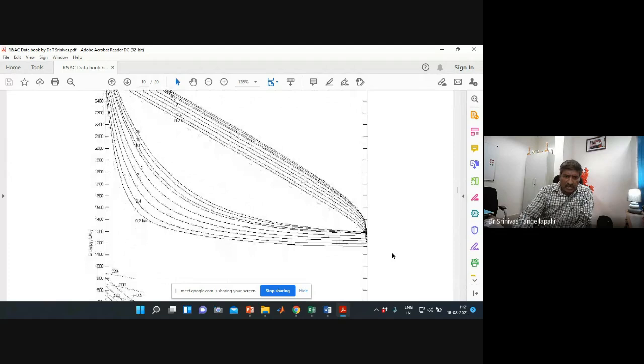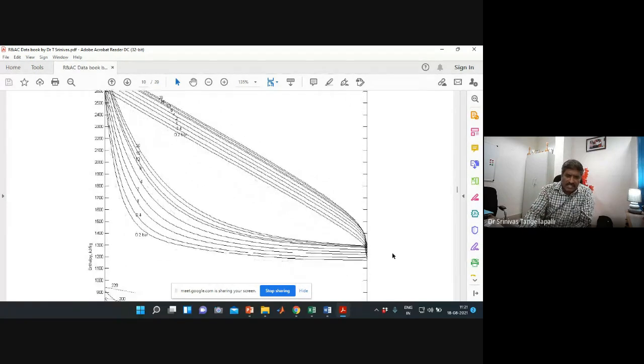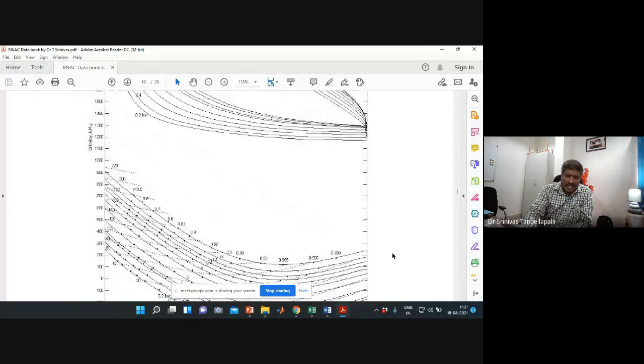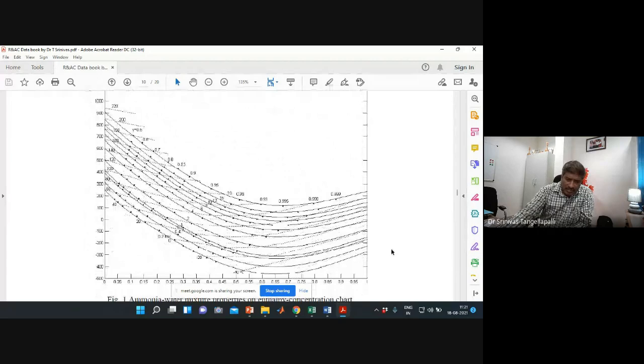Also, I am going to include one more chart. This chart is suitable for solving the cooling system and refrigeration system. You may see 3 sets of curves here: the liquid, auxiliary, vapor. These are the saturated liquid. You can also see the temperature curves, which are then shown in the right-hand sketch. These are saturated liquid as usual. There is a temperature, yes, 220, 200, 180. These are all the dotted lines. Blue dotted lines show the temperature. These are the temperature curves.